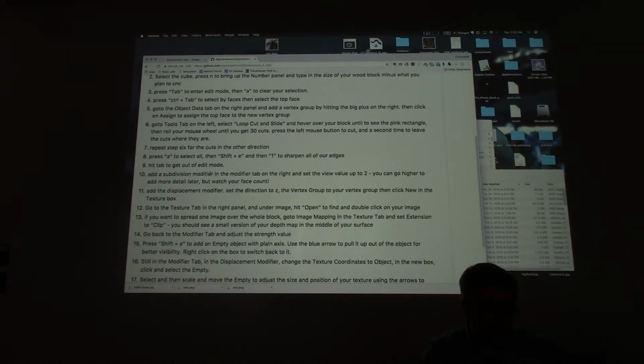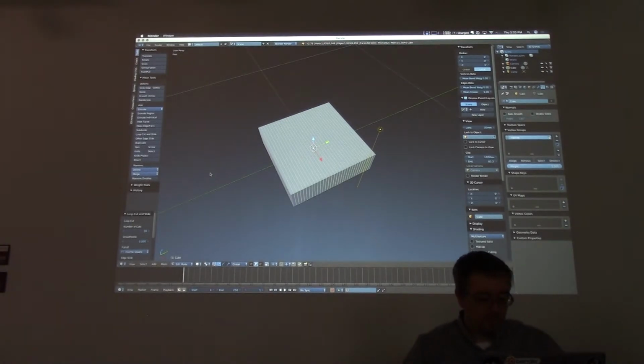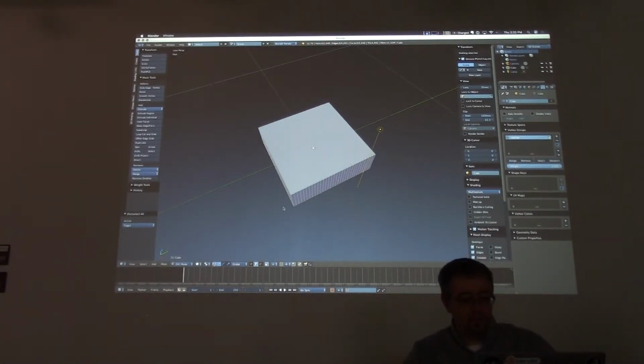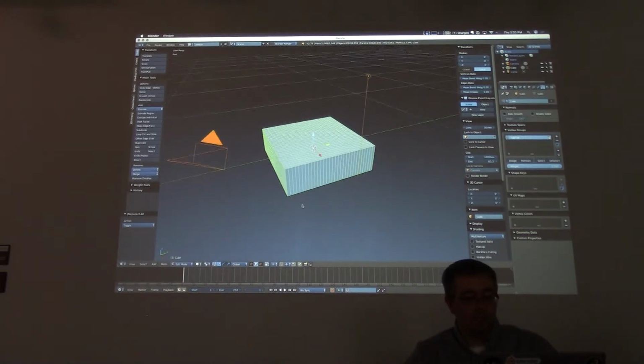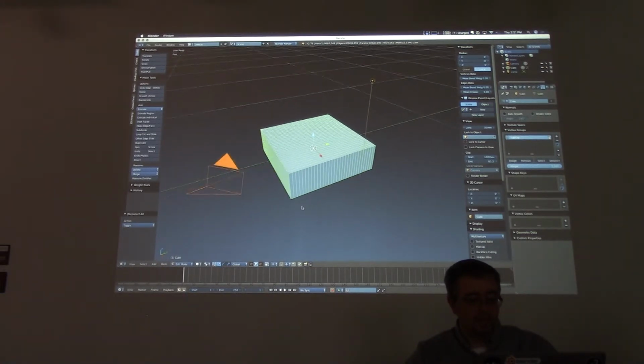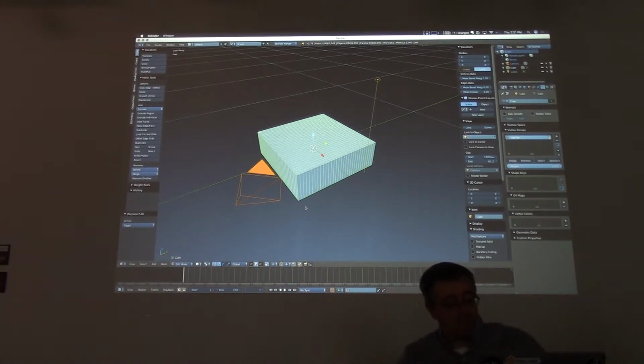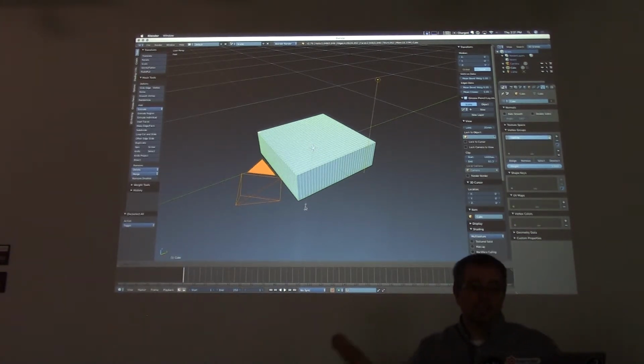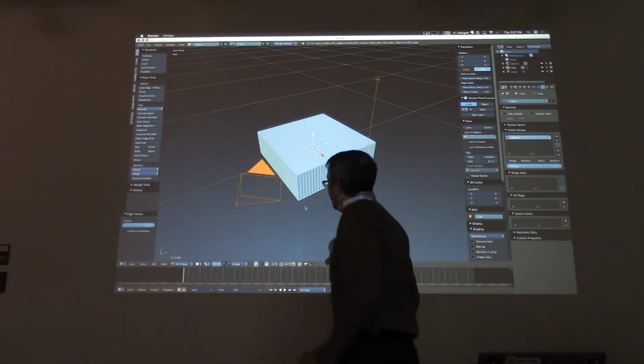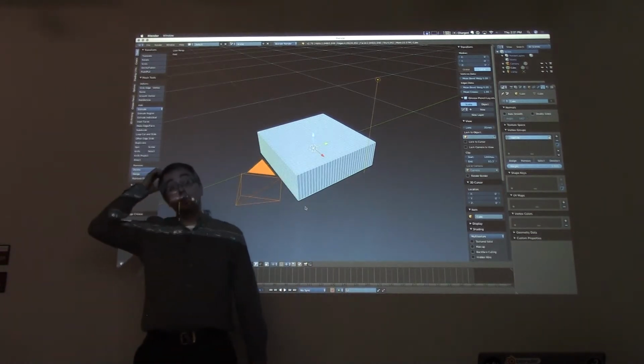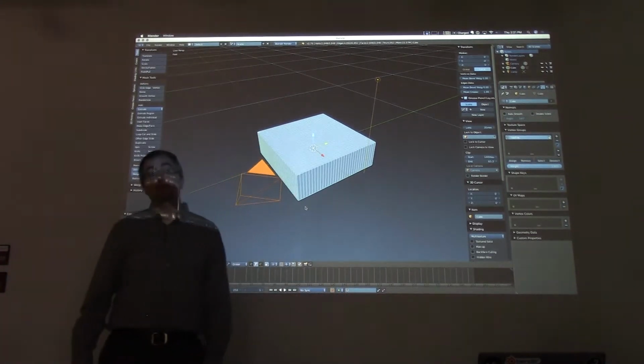And then we're going to sharpen all of these edges. So the next thing I'm going to do is press A to select all of them. And again, they glow. And then I'm going to do Shift E, which is for sharpening the edges. And this has to do with subdivisions that we'll do later. And then I'm going to type the number 1. And what that means is sharpen all of these edges to their fullest extent. What's their original state? 0. So it'll round them as much as it can.